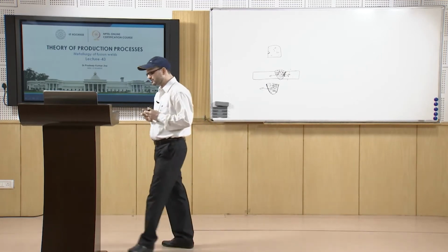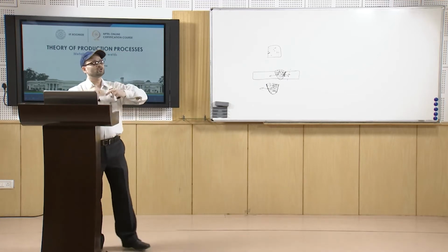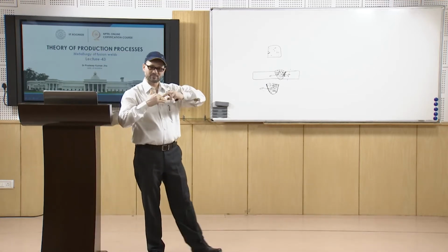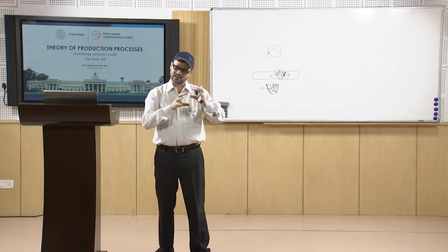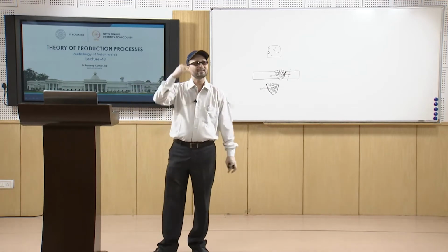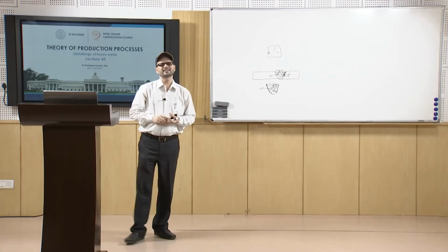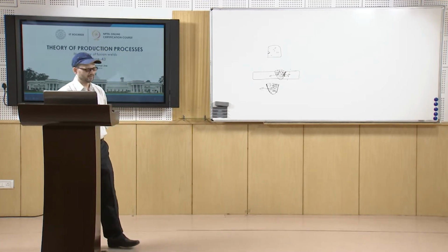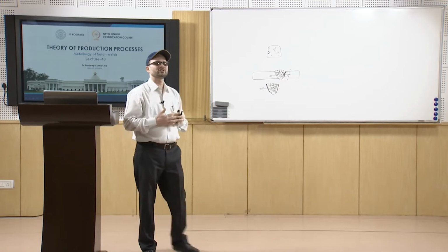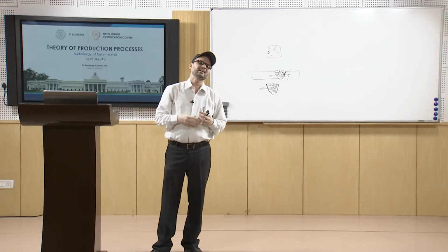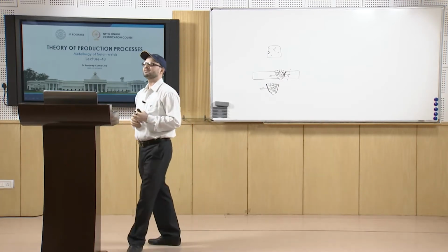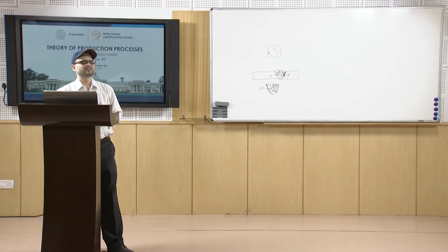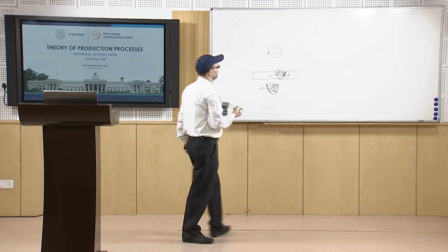When these two are parallel, the grains grow, otherwise they are pinched off. That is known as competitive growth. Ultimately, this competitive growth concept is effective in welding, and that is how you see the formation of the grains.